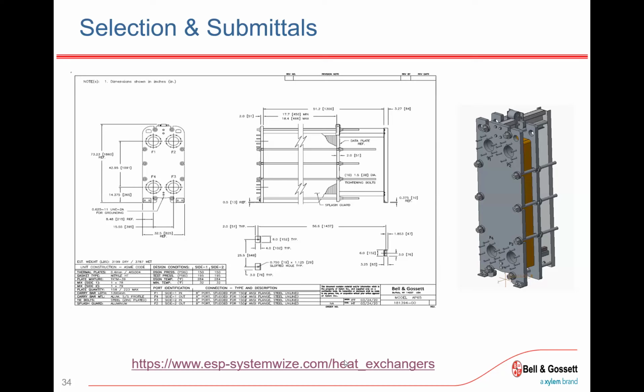This is where you'd select if it's water to water, a single phase item. If it's a steam condenser, so if we're looking to use steam in the unit, like a steam to water application, then do steam condenser. It's all pretty intuitive. So let's go in and take a look at that heat balance equation. If we were to have 60 gallons a minute, 120 in, 100 out, 60 gallons a minute, 70 degrees in, we have enough here that this will tell us the load, right? So we've got inlet, outlet, and flow rate that gives us a load.